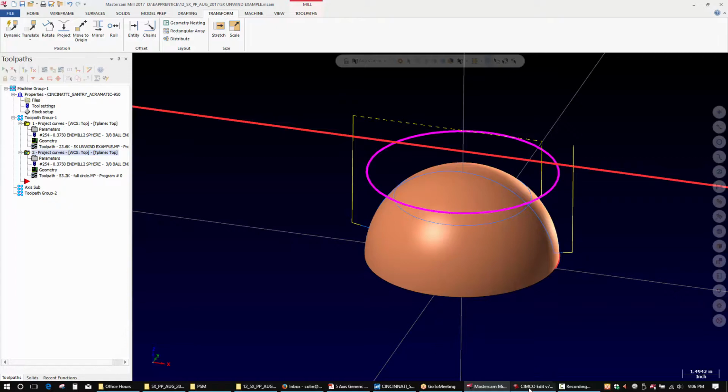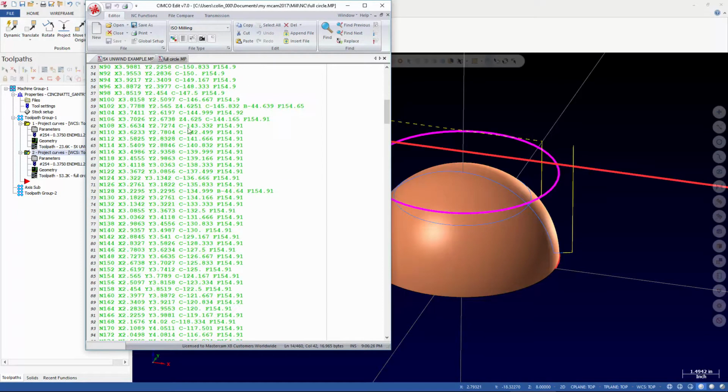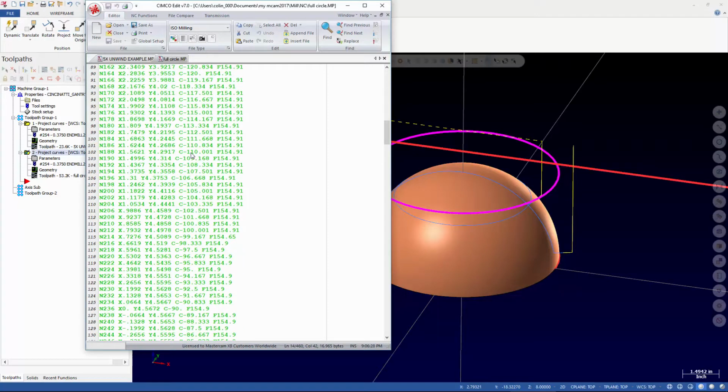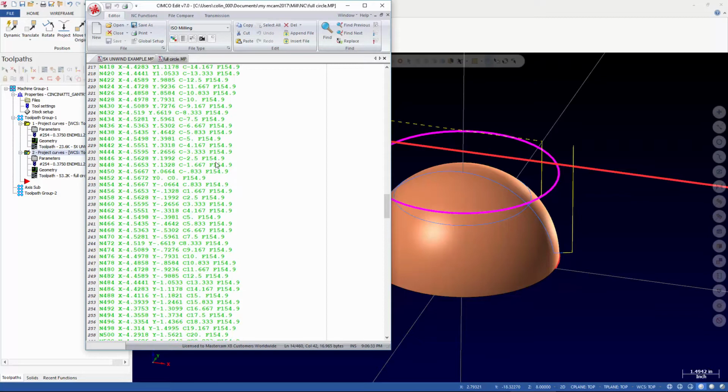Well, first of all, let's continue looking here. So we start negative 180 and we go down, down, down, down. But what I'm looking for is what happens when we cross over. And specifically what I'm looking for is, does it just cross over and keep on going, or do we get something funky where it tries to flip the secondary axis on us? Because sometimes that'll happen in the code without retracting. You have to be a little bit careful about how you're setting this all up.